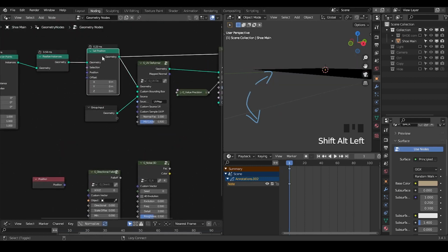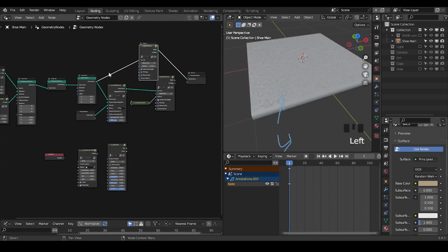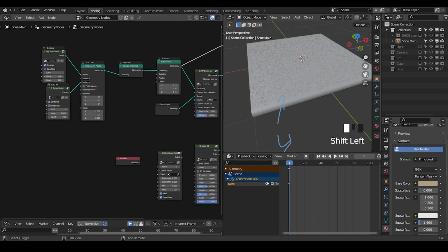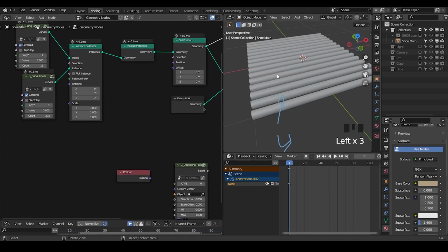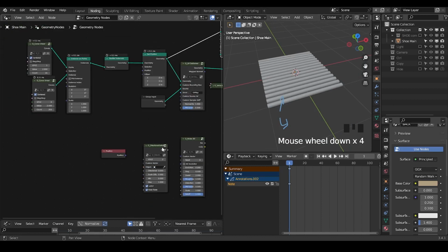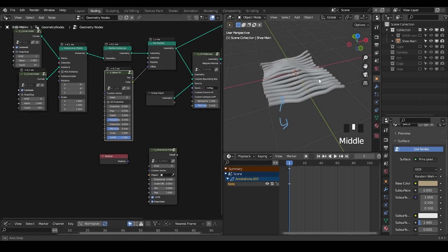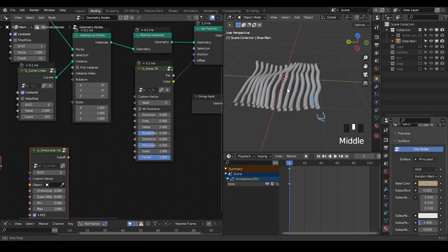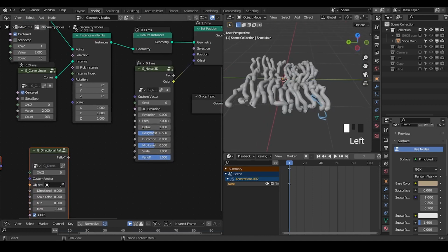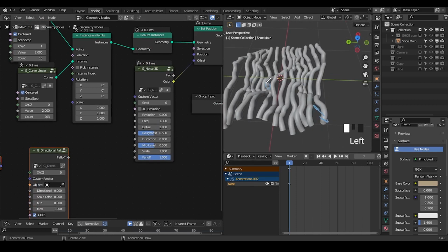So let's take a look at this 2D space. For better visualization, I'm just going to use the bevel curve to give it some volume. And I'm going to decrease the count just for better visualization. Okay, and you can directly plug this noise 3D into the object, then immediately you have noise. This noise looks very continuous. If you want to make it very discontinuous, then you increase the frequency, but then it becomes very ugly with all these knots.